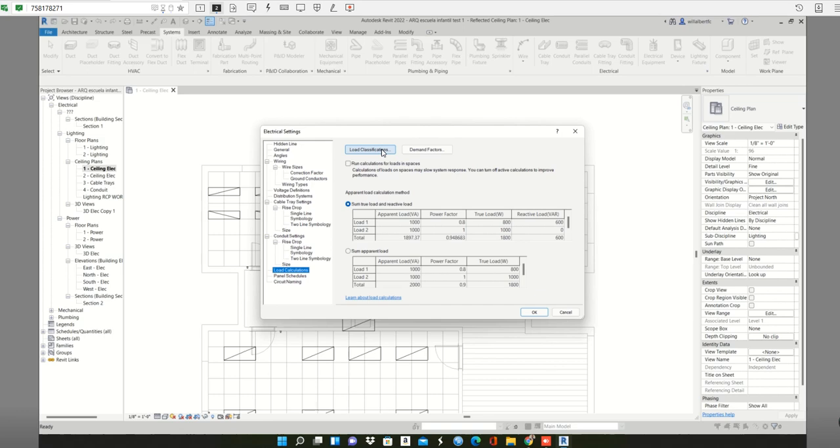Let's suppose that it's not a house; it's a 24-story building. It's very likely that all the people are going to use a lot of water in the morning from 6 a.m. to 8 a.m. because everyone is preparing for work, right? And they use these demand factors to estimate, and by code.